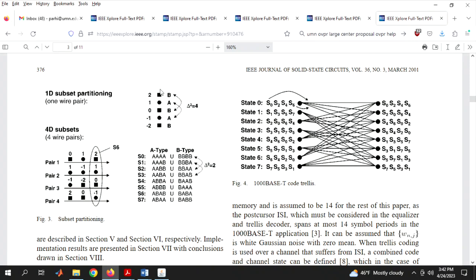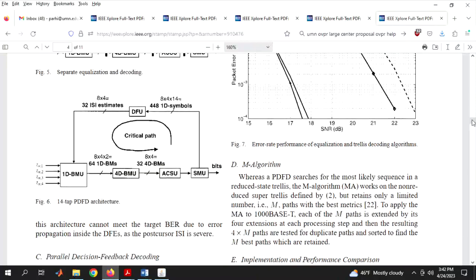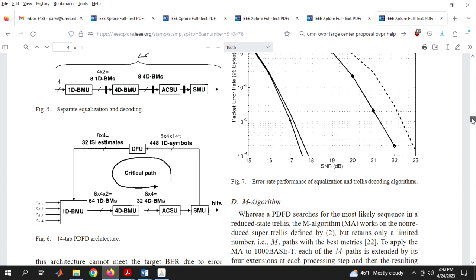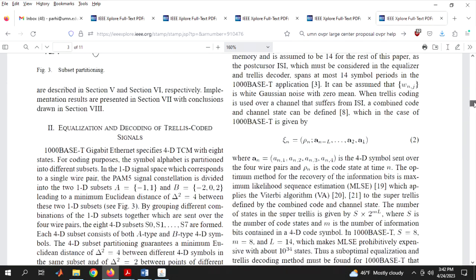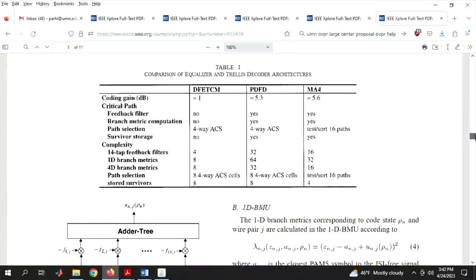But the 5-level PAM5 that I talked about has values 0, plus minus 1, plus minus 2. Those are the 5 levels. All the decisions with respect to those 5 levels can be pre-computed. So that's the long feedback loop, similar to the quantization loop that I showed. For the 5-level decisions, they can be pre-computed and pushed outside the feedback loop, and that really enabled these